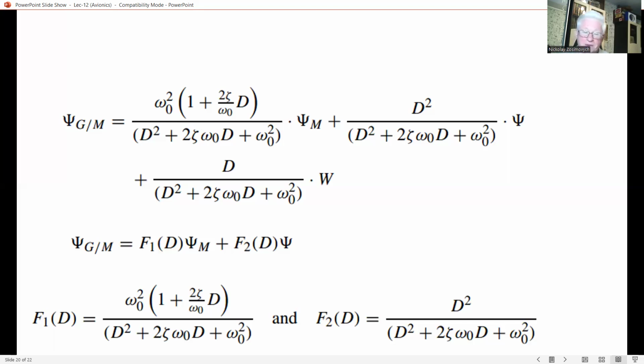The integral feedback gain, in our case K2, determines the undamped natural frequency. And the proportional feedback gain, K1, determines the damping. So K1 and K2 are determined by the value of the gyro bias uncertainty and the need to have a well-damped closed-loop response, with zeta equal or near to one.